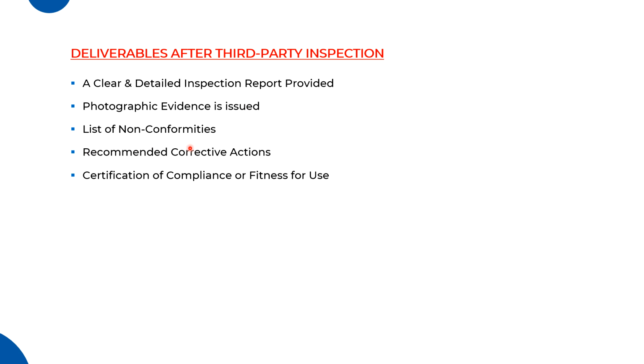A list of the non-conformities: what the non-conformities are, and what needs to be rectified. Remember that if non-conformities are in major status, they cannot be ignored. Unless they are remediated, solved and rectified, the drilling will not be started. The third party who will rectify it will again do the pressure test and the inspection, and he will give the certificate of fitness to the rig contractor. It ensures that the equipment is now ready to be used. Now the contractor can start the drilling.